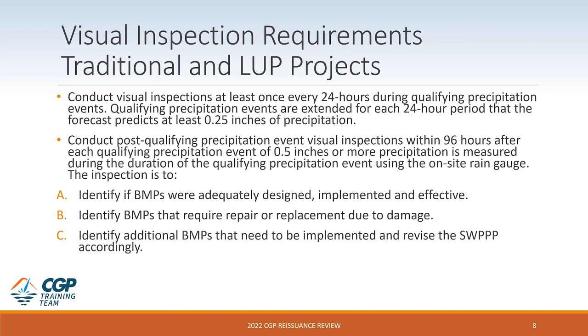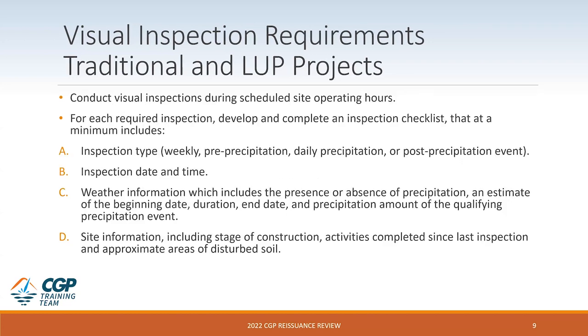Now, this inspection is to identify if BMPs were adequately designed, implemented, and effective, to identify BMPs that require repair or replacement due to damage, or to identify additional BMPs that may need to be implemented and to revise the SWPPP accordingly. We conduct our visual inspections during scheduled site operating hours.